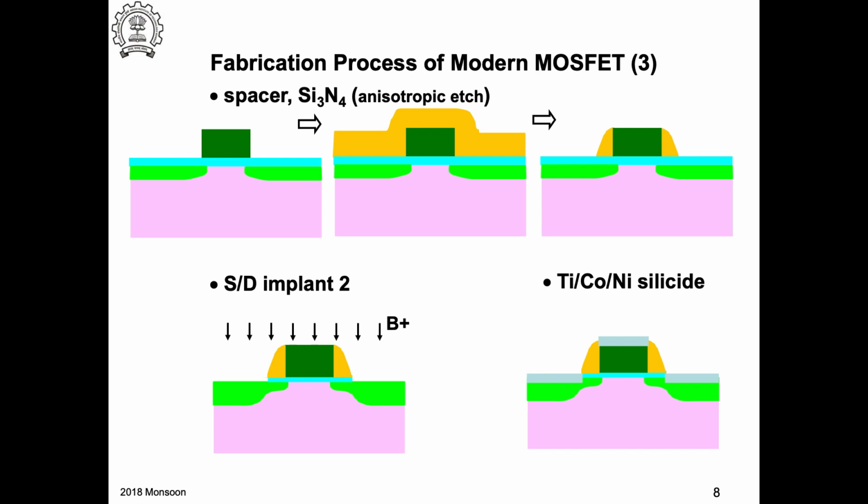I'm talking about how to design a mask for an implantation. If it is very thin, I have this kind of problem. Which shape? Oh yeah, there is something called stopping power of ions in the material into which you are implanting. So the stopping power would depend on how heavy the element, the atom, is. Let's say I am implanting boron into photoresist and silicon. Silicon being heavier than carbon, meaning photoresist is usually organic, you would have a slightly higher stopping power in silicon than in photoresist.